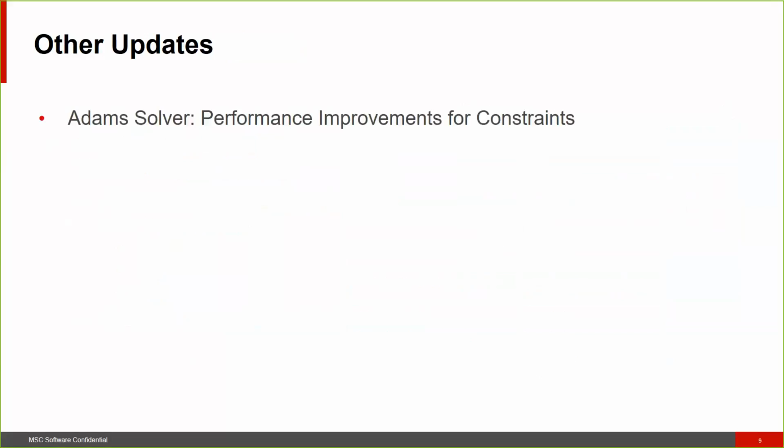We've seen performance gains of around 5 to 15% if you're looking at models that have a significant amount of content in these object types and don't have significant content in other, let's say huge, compute-thirsty components like flexible bodies and contacts. This benefit can be experienced with any Adams Solver integrator type, but we've seen it especially with GStiff SI2.